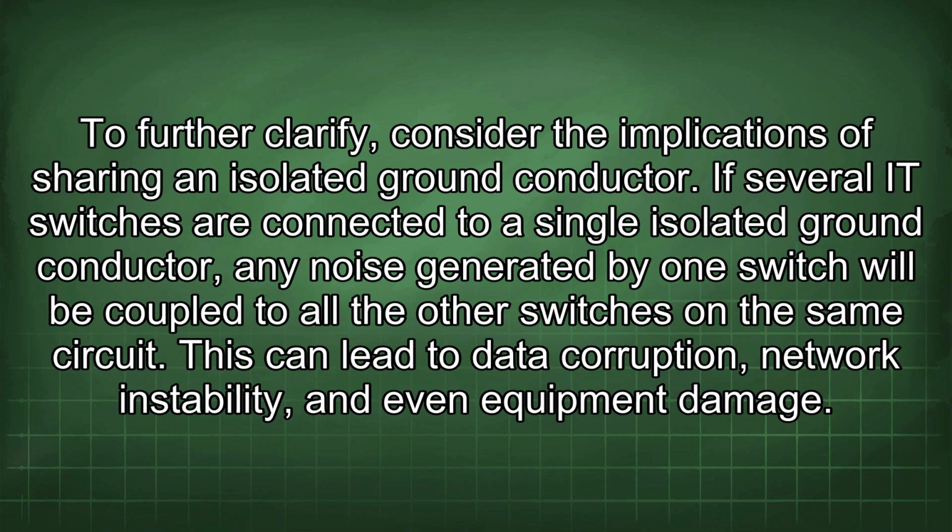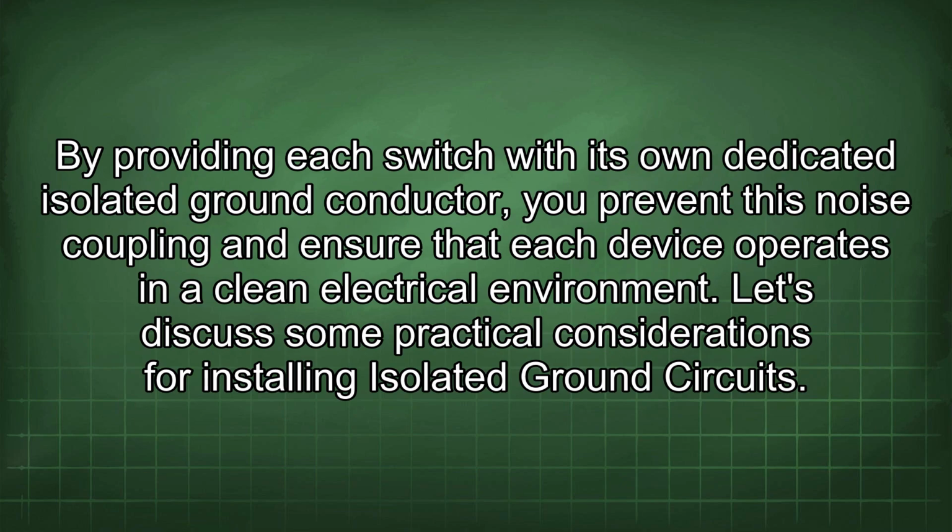To further clarify, consider the implications of sharing an isolated ground conductor. If several IT switches are connected to a single isolated ground conductor, any noise generated by one switch will be coupled to all the other switches in the same circuit. This can lead to data corruption, network instability, and even equipment damage. By providing each switch with its own dedicated isolated ground conductor, you prevent this noise coupling and ensure that each device operates in a clean electrical environment.